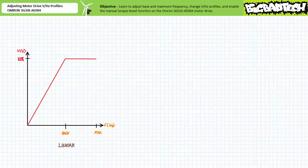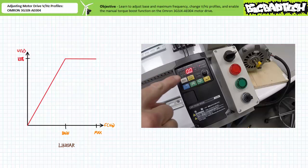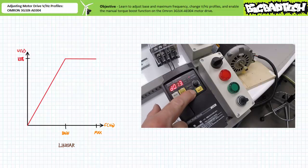When we start the motor with the external speed potentiometer pegged fully clockwise, excitation frequency ramps up to only 60 Hz this time, as we'd expect. The motor accelerates and speed stabilizes. While the motor is running, we can navigate to parameter D013, output voltage monitor, and find the motor drive is applying roughly 100% of the available line-to-line voltage.